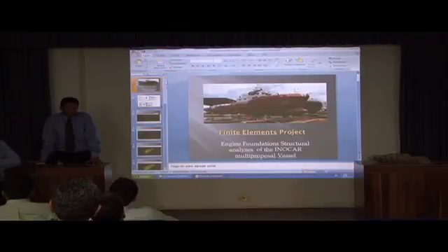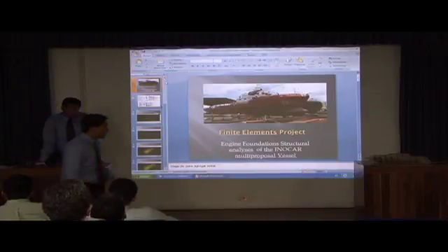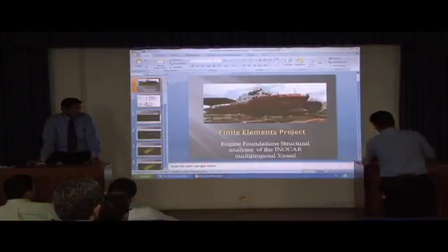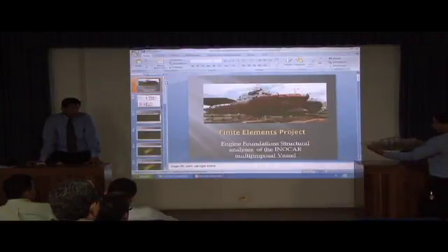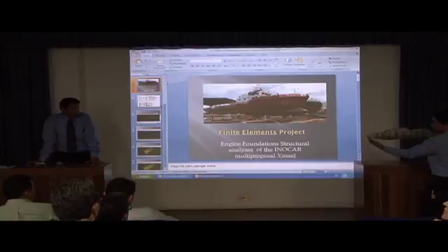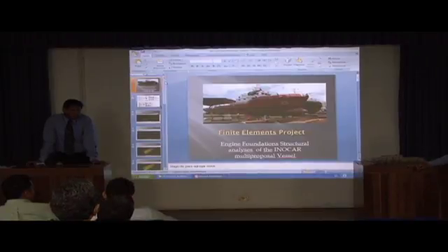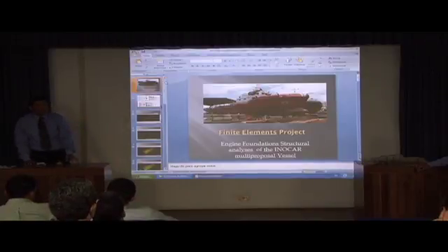Any other question? Just for some doubts, we were on the docking plan, and we put the blocks in this way. That's why it's the analysis. We put a block right here and the other here, so it behaves like a beam, and the spacing is really big. So it's the worst condition in which we can analyze the structure, not in water, just in dock. So the structure can fail in that case. Thank you.